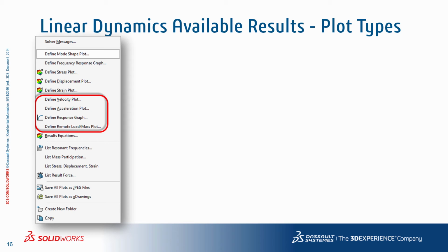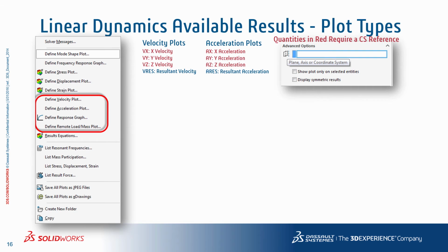While working with linear or nonlinear dynamic studies, in addition to stress, displacement, and strain plots, you also have access to velocity and acceleration plots as shown. Note that the ones highlighted in red require a reference coordinate system as described earlier.